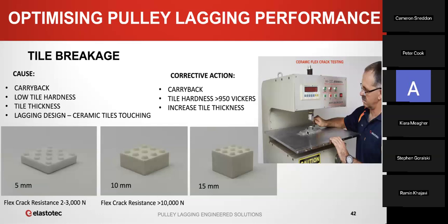So this machine here, we put the tile in little jigs so that the tile is held on each side. And then this plunger comes down and applies a load to the center of the tile. And we measure the force that's required to crack the tile. Now, a 5 millimeter tile will crack with 2,000 to 3,000 newtons of force.